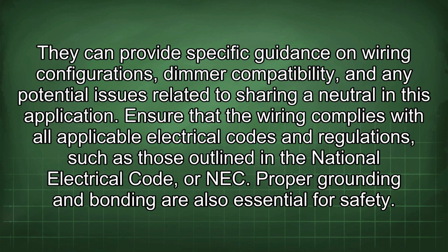They can provide specific guidance on wiring configurations, dimmer compatibility, and any potential issues related to sharing a neutral in this application. Ensure that the wiring complies with all applicable electrical codes and regulations, such as those outlined in the National Electrical Code, or NEC. Proper grounding and bonding are also essential for safety.